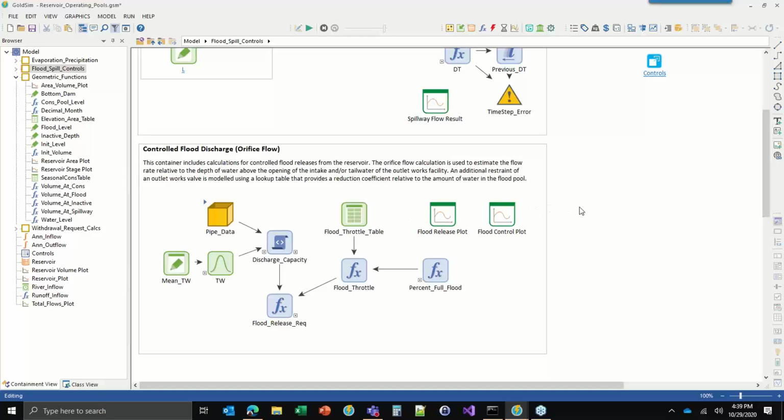It's just we want to control the flows, release the flows at a controlled rate, and in this case it's done using hydraulic calculation based on the pipe length. So it requires iteration to solve, because the flow does affect the head loss because of friction. And so it's an iterative solution to solve that in this case. But you might not have something that complicated.